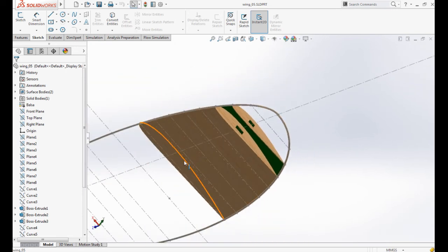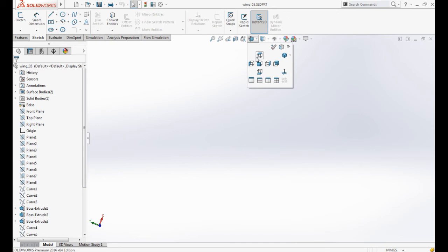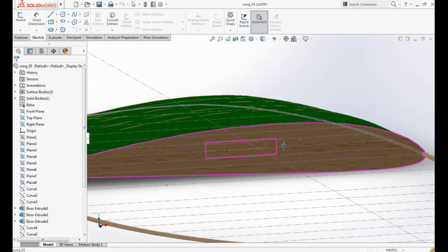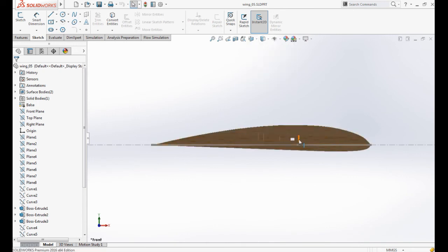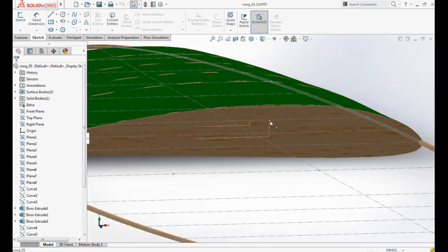Remember that you will need the space for the spar, which should have angles, not a circular tube, but a geometry with an angle, because if you make a spar with a circular tube, you can have the rotation of the airfoil along the spar axis. So try to choose the right geometry here. See the previous video for this issue.